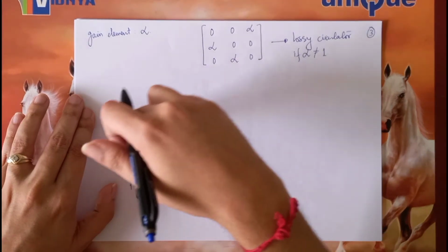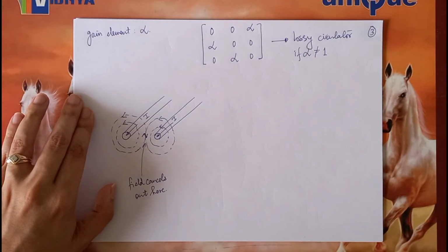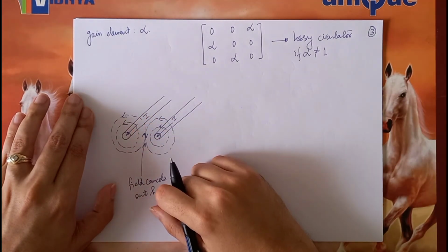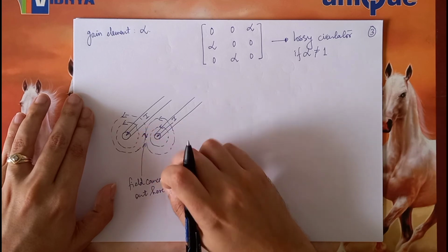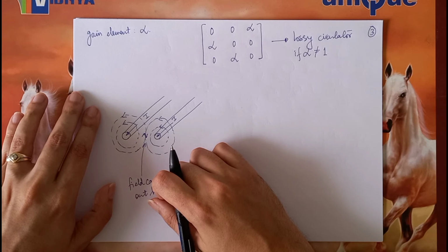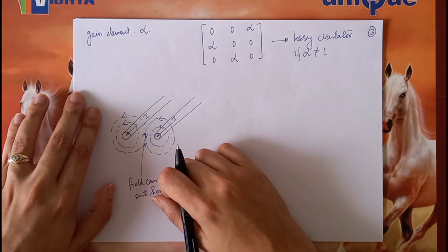So therefore there would be an open circuit. Whatever the electric field is, that's not our concern at the moment. What is important to note is that the current would become 0, which indicates the middle is kind of like a virtual open circuit. And that is the basis of the even mode.